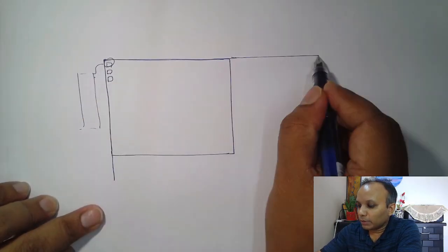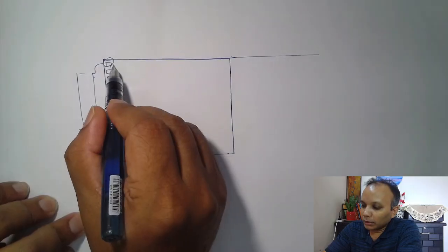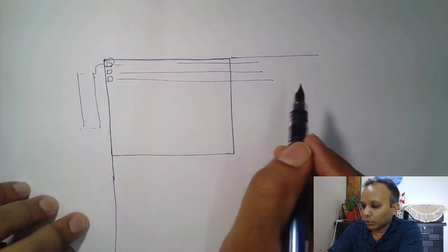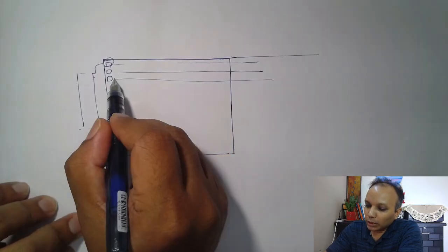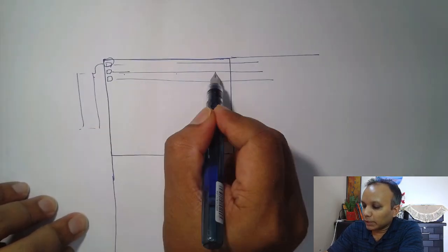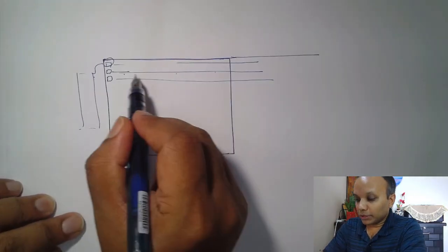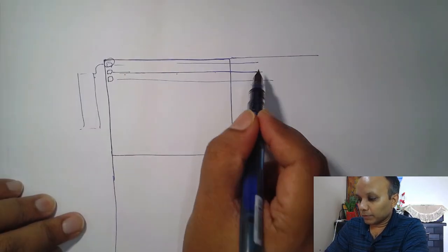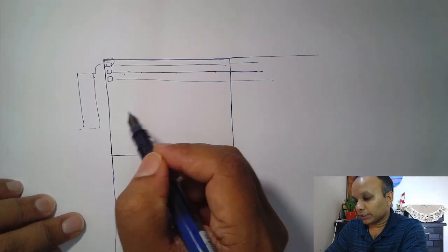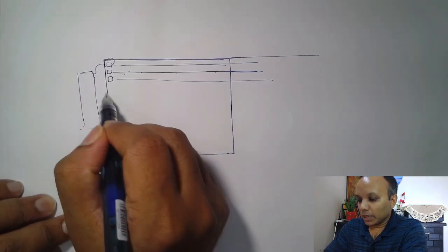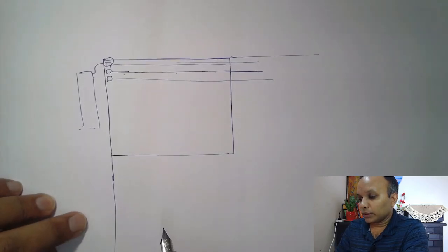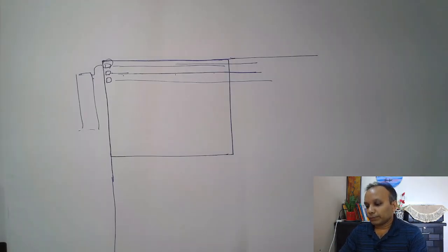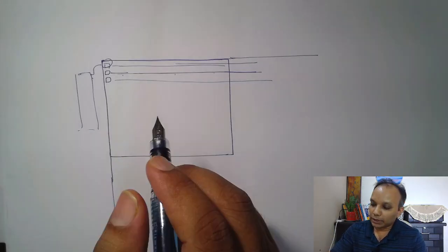Now, as this memory becomes bigger and bigger, these wires connecting these different rows or different columns become longer and longer. Now, they introduce physical limitation. So, the time required or the amount of charge required to basically charge these wires or discharge these wires becomes very high, and as a result you can't really do these read write operations very fast in your main memory because of the physical limitation of how the memory is designed.